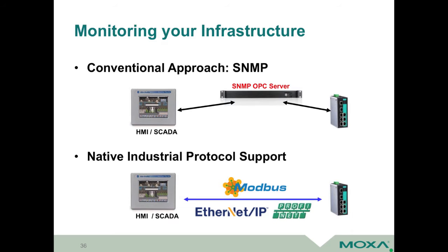So let's say you've got that managed switch out here, and you'd like to get that up to your HMI. Well, guess what? A lot of managed switches talk Modbus TCP now. So if you wanted to have an HMI screen or a SCADA system show just some simple network health monitoring, you can see which ports are connected and which ones are not on a special screen you've designed, just adding those data addresses for those individual data devices in that managed switch over here.